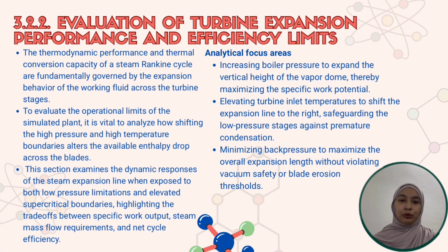Next, in section 3.2.2, we evaluate the turbine expansion performance and its efficiency limits. The thermodynamic performance and thermal conversion capacity of a steam Rankine cycle are fundamentally governed by how the working fluid behaves as it expands across the turbine stage. To evaluate our operational limits, it is vital to analyze how shifting high pressure and high temperature boundaries alters the available enthalpy drop across the blades.